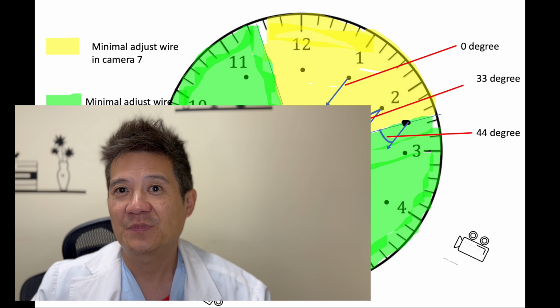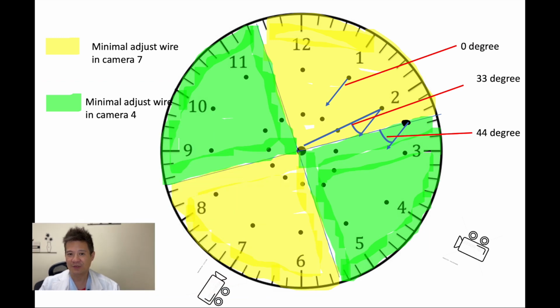So we said the rotation, if it's the same distance between the two views, we rotate 44 degrees. If it's half the distance in the second view, 22 degrees. If it's a quarter distance, 11 degrees. And this is the diagram that illustrates why that works.